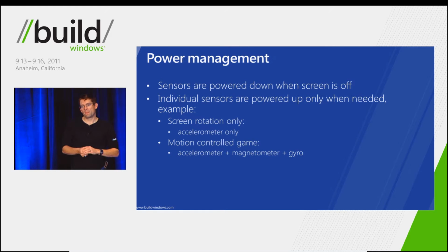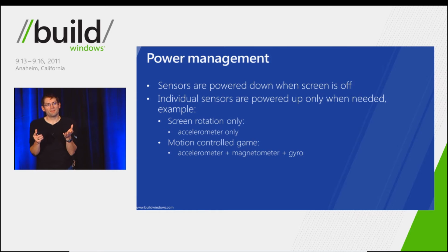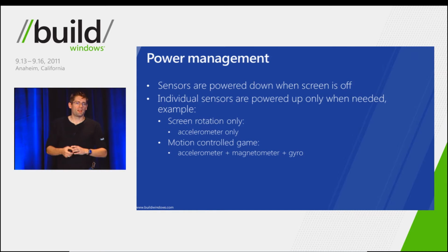When an app starts up that uses any of those sensor fusion sensors, the hardware needs to respond by altering that power state machine. If we have an app that's using the device orientation sensor, the gyro needs to get powered up, the magnetometer needs to get powered up, and then the device orientation needs to be determined in a reasonable amount of time. If a game is starting and has a 2-second splash screen, ideally when that splash screen is done, the sensors are brought up and the net knowledge of device orientation is ready for apps to leverage. So power management is critical.